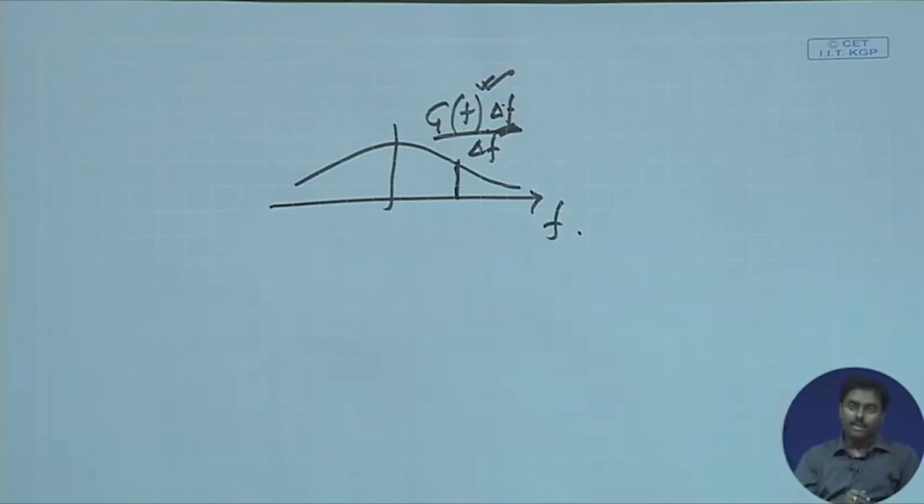Often we make that mistake, and in many books also you will see that they just represent it as spectrum. So, they say for a particular time bounded signal I do Fourier transform and then I plot GF, that is actually my amplitude spectrum. It is not, or modulus GF I draw, I get amplitude spectrum. It is not, it is spectral density, it is in no way spectrum, because the spectrum is GF into del f, which has no value. It will be 0 everywhere if I try to plot that. It is just the density which has some meaning over there.